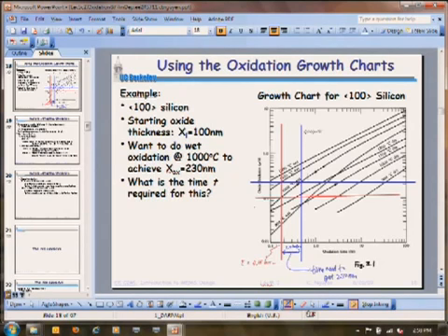How many wafers do you have in the tube? All of those things. So when you're designing a process, thicknesses you can get fairly close to what they need to be, but you can never say that you're exactly on. Okay, so a lot of times this is good enough. Who knows? Maybe the equation can be a little bit better, and so if you really need to be accurate, I would use the equation, right? But usually, if you have something that requires that kind of accuracy, probably not a good product anyway. Okay, so this is how basically people do it out there, and I just wanted to show you this to make sure you can do that for this class. All right, so keep going with oxidation at our extremely fast pace.